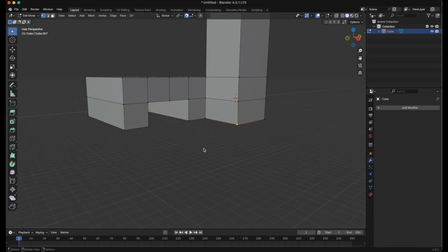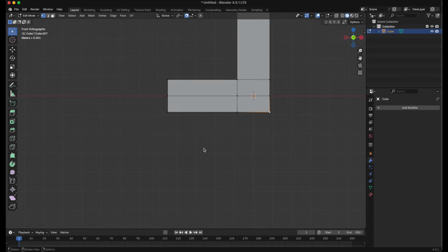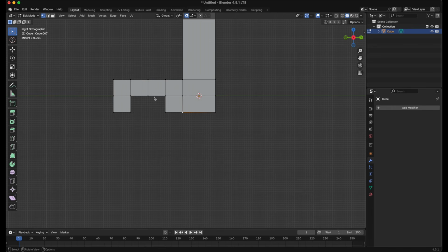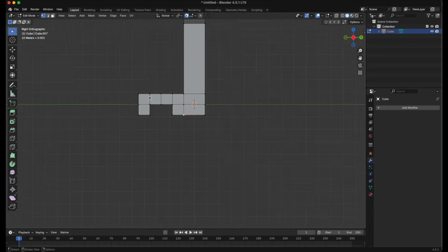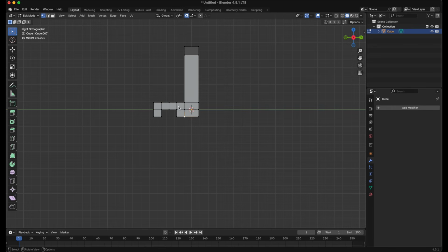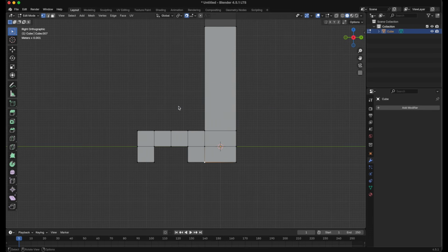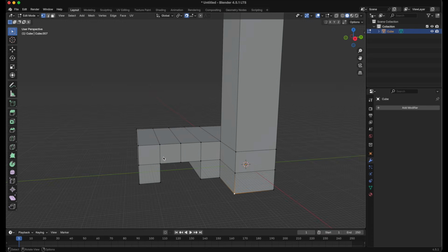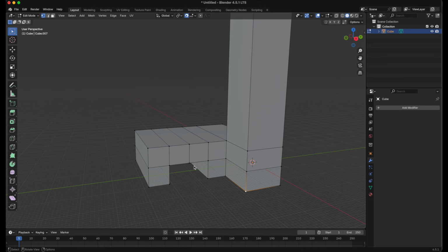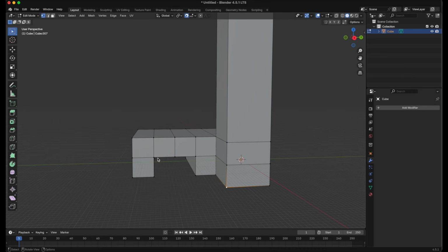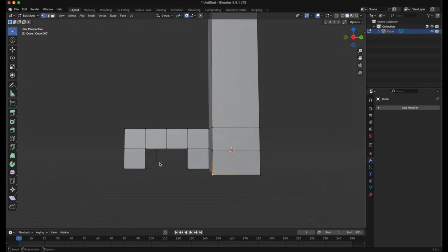Now our object here has, if I go to the front view or the side view, you'll notice this is technically an overhang, because we're printing up in this orientation like so. So technically, this is I would say a 100% or 0% overhang right here. But because it's perfectly horizontal, the 3D printer can actually bridge across this overhang, technically kind of 3D printing in mid-air. So it's super cool with 3D printing.